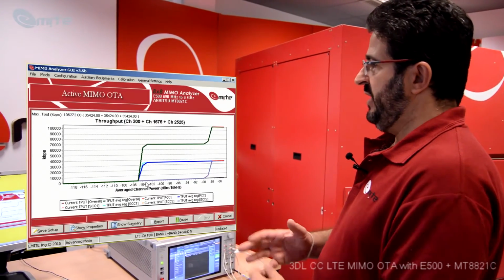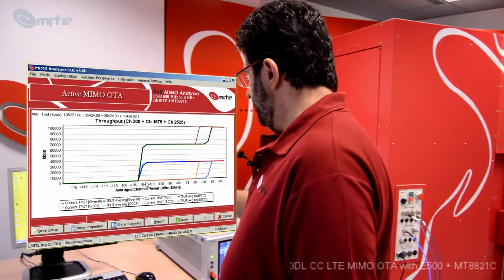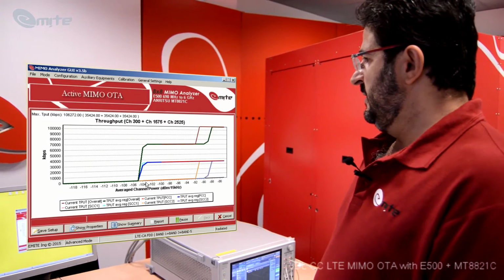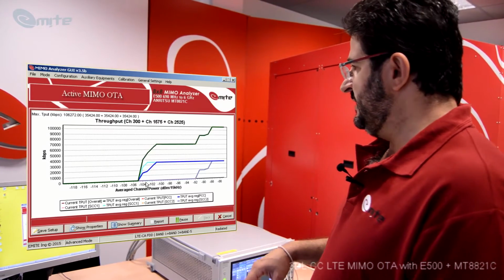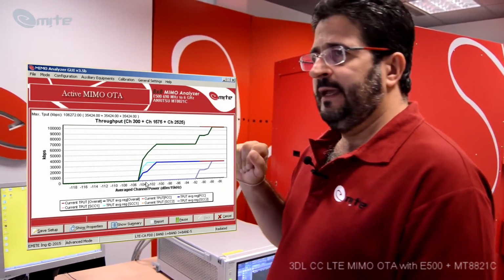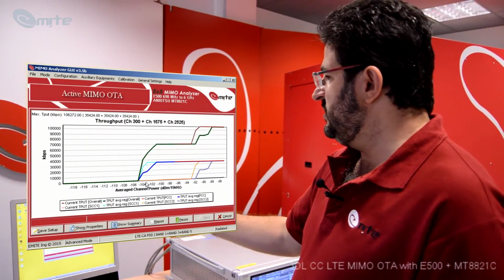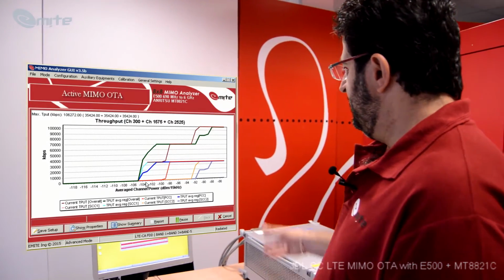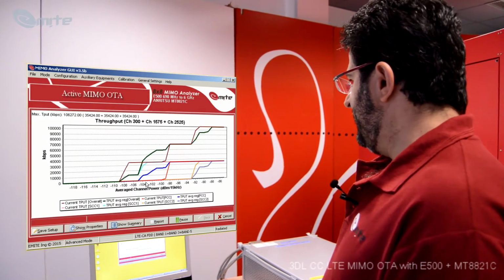That's basically the primary, the first secondary, and the second secondary curve here, and overall that gives you the entire throughput provided by the device. Now, the way the throughput is being measured in the reverberation chamber is that you have a sample that is being measured continuously, and once you get a sufficient number of samples, those are averaged to get the final curve. So this is why you see on the screen a number of curves evolving, and then as we collect samples, those are averaged out into the final value.